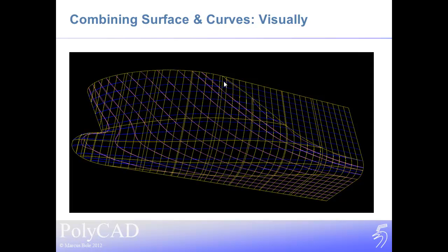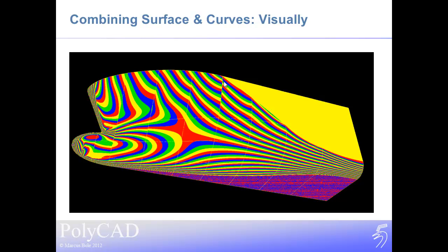So I need a little example to show this process. So this is that original surface that we saw there earlier. It would take some time for me to go through and improve that surface in front of you. So we'll highlight the improvement that we can achieve with some isophotes. So these are the light falling on the surface and the different colours of curves show the angle the light makes with the surface. So we see around the flat of side area around here, we can see quite a big discrepancy in the tangency between these two curves, basically meaning that we haven't got a very good smoothness in the surface. And that's also a case around the bow, around the bulb.